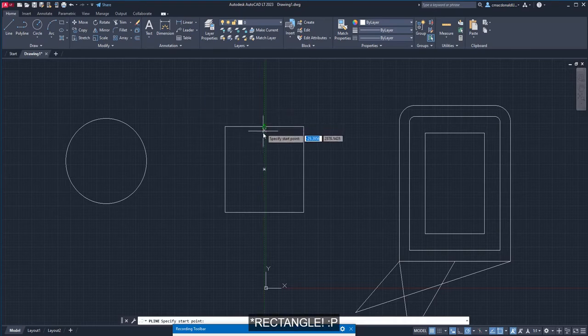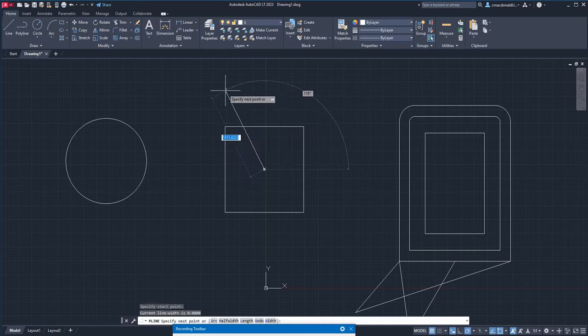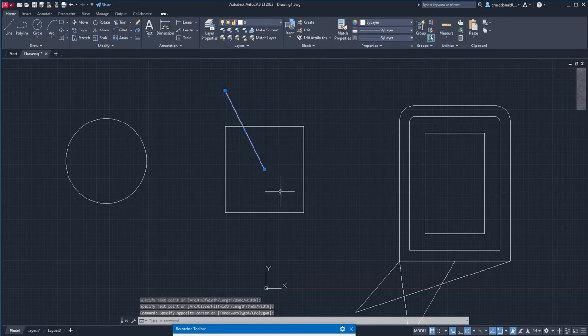See there? Look at that little asterisk in there. That's the snap telling us that that is where it thinks we want to snap the line to. Let's try it. Let's left click where it's illuminated. And now that line originates in the geometric center of that rectangle.